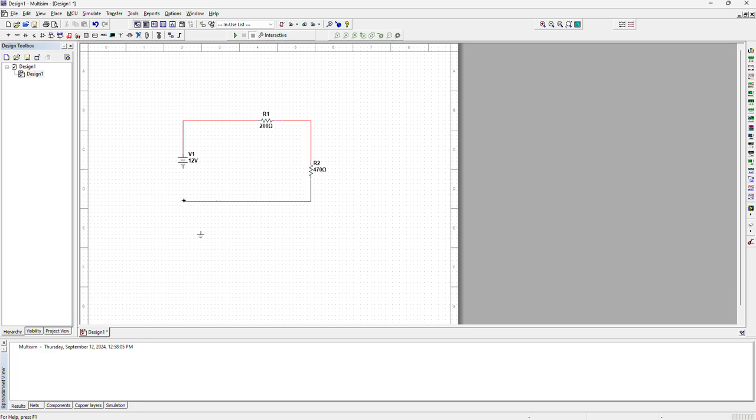So I'm going to go ahead and do that and drag over. Now you'll notice instead of drawing a wire down to this ground, all I did was go over, and you see how it kind of connects? It creates that dot. As long as you see that dot, you're connected. See, if I drag it down, I'm still connected. It just extended the wire out. So that is an option.